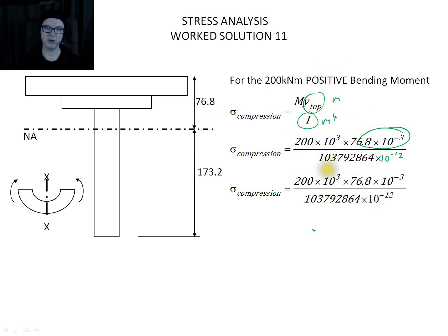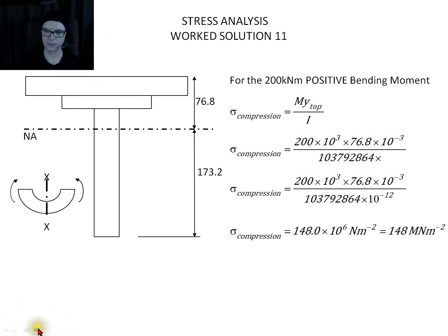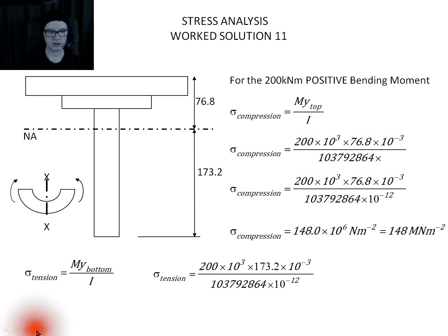So this tells me we've got a positive load, sorry, you've got load from above, positive, which causes a positive moment, which will cause me compression at the top. Okay. And now I can look for the tension on the bottom.